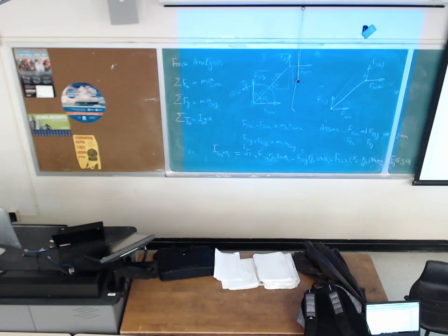Most likely tomorrow, we are gonna derive 9 equations and 9 unknowns. What would be 9 equations? What would be the 9 unknowns? I have 1, 2, 3, 4 joints. Each joint has 2 forces, one in x direction, one in y direction. 4 times 2, 8.